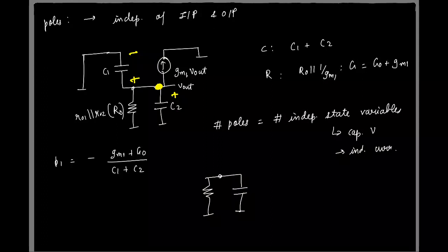Of course, like he's saying, this trick you can't apply everywhere. For example, if you have a more complicated network, simply looking at the capacitance at a node, the resistance at the node, and taking the 1 by RC will give us something, but whether it will be the exact pole is questionable. Also, when you do this, we can only get real poles, but poles can be complex.